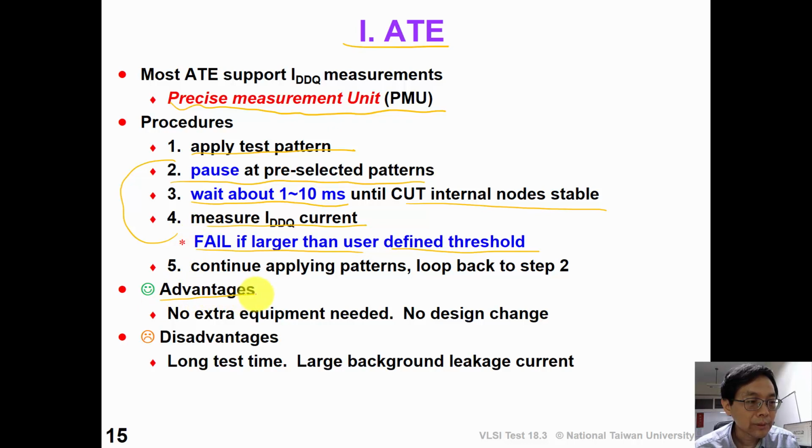The advantage of this method is that we don't need extra equipment and we don't need to change the circuit design. However, ATE measurement suffers from long test time. Also, the background leakage current is large.